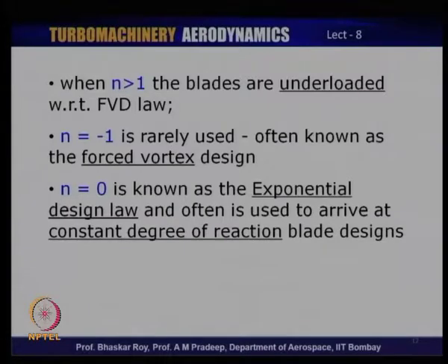As a result of which, you never get the full loading anyway, because of its three-dimensional flow nature, especially near the hub and the tip, in which case the blades are not going to give the same blade loading, same pressurization near the tip and the hub. As a result, many designers now feel over the years that there is no point loading the blade so much near the tip and the hub, might as well underload